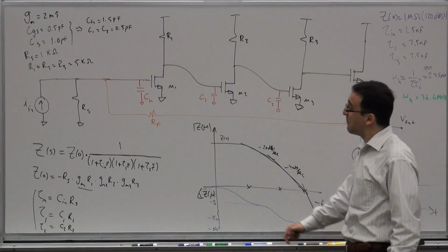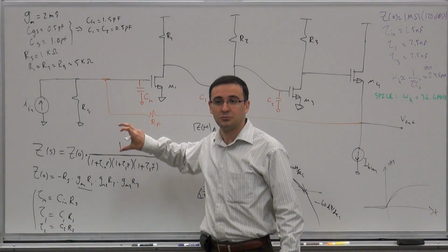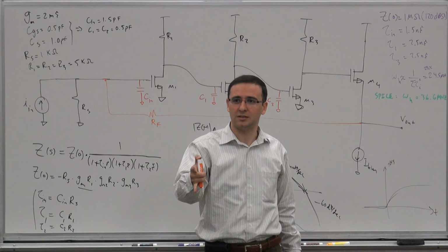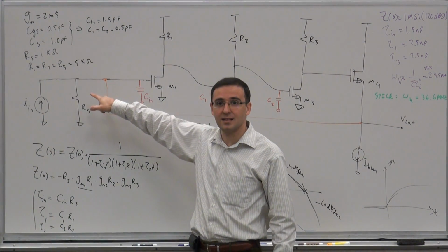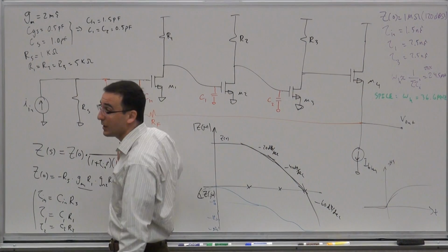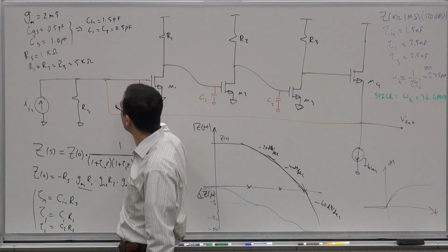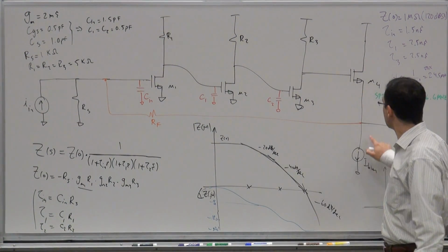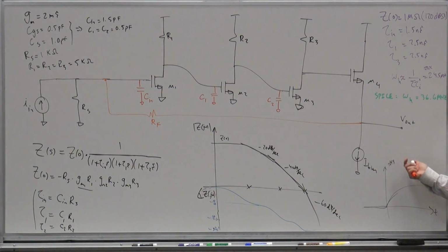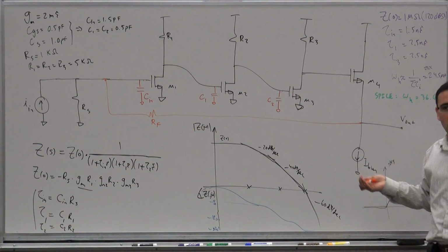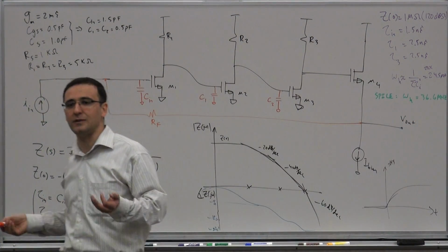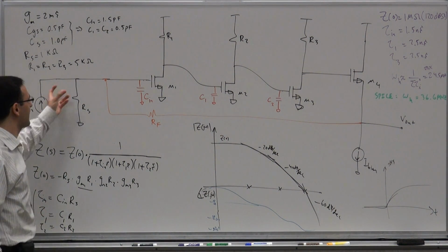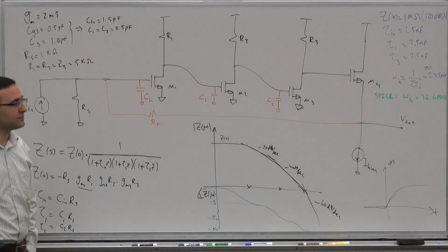So it makes the input a better current meter, because an ideal ammeter has zero input impedance. If you are trying to measure the current, more of the current will go in. You also expect it to reduce the time constant of the input, since you reduce the resistance here. At the output, it lowers the impedance, which makes a better voltage source. So this is the right kind of feedback to use to make a transimpedance amplifier, something that takes a current in and produces a voltage at the output.